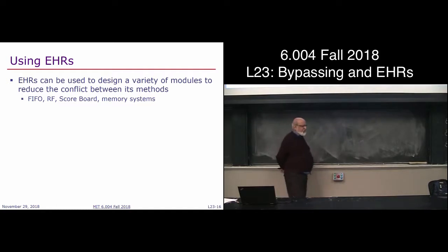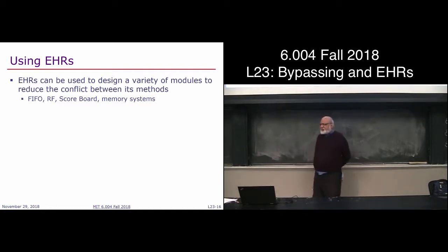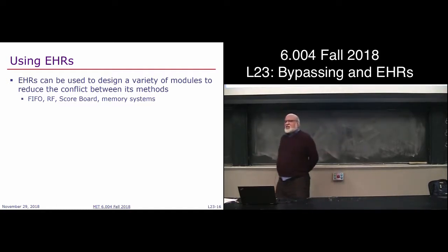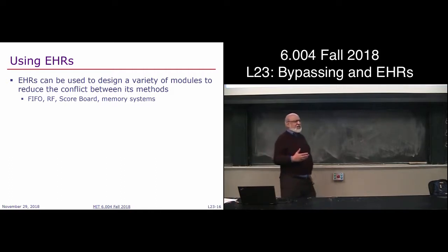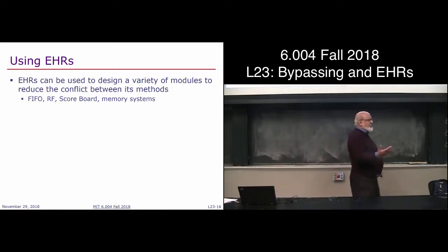But you can do scoreboards this way, you can do memory systems, and provide so many variants. In some places in a memory system, we absolutely cannot afford to lose a cycle, because it will have drastic consequences for performance. In many other places, we don't care if an extra cycle gets introduced, and if you're wasting too much time with bypasses there, you're wasting time.